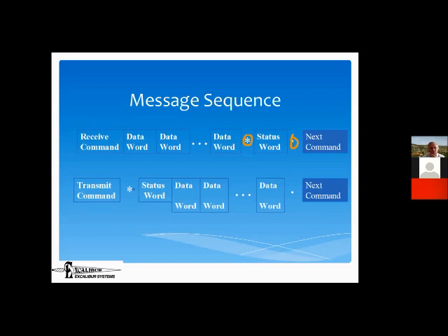Another question was asked if Excalibur cards support less than 4 microseconds response time. It's actually not legal to have less than 4 microseconds response time, and we do not. In fact, depending on the message types, we're usually closer to 7 or 8 microseconds. And in fact, very few people get to the minimum,